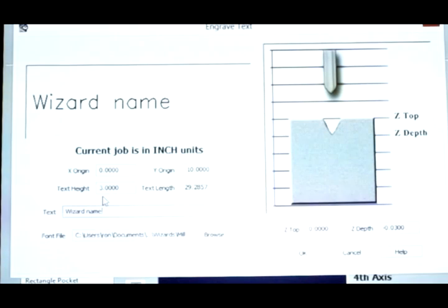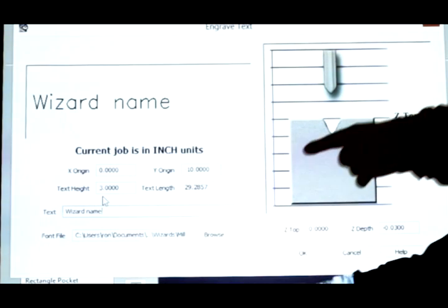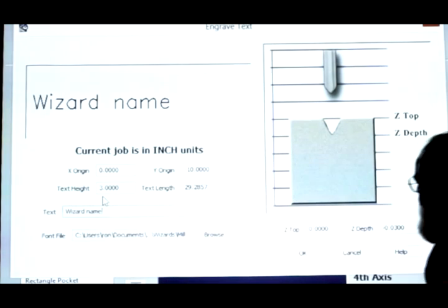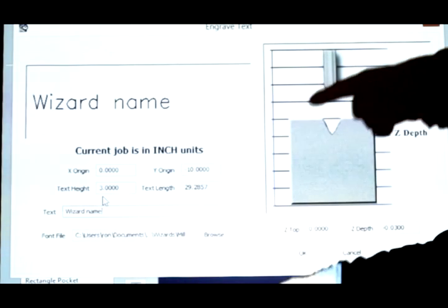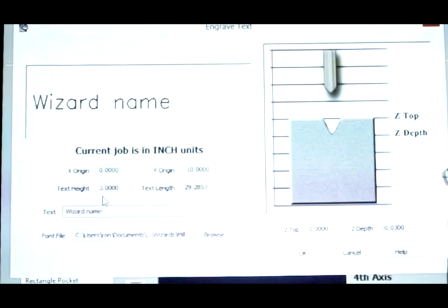It's using the same font file, okay? And it gives you, this is Todd's insistence, a length. Right now I'm asking for 3-inch tall characters, and if I want to type that in 3-inch tall characters, I better have 29 inches. It's calculating how long this string is. You don't get to enter that. That's a box that won't allow input, okay?